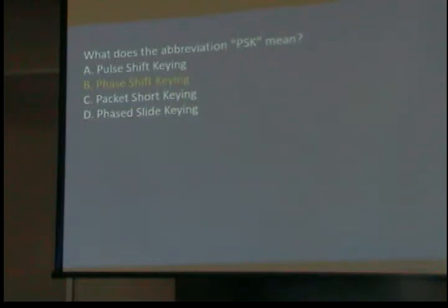Okay, what does the abbreviation PSK mean? It is phase shift key. It's just something to remember. What it does is it's a modulation method where you change the phase of the signal, the peak and valley phase. You either delay it or advance it.